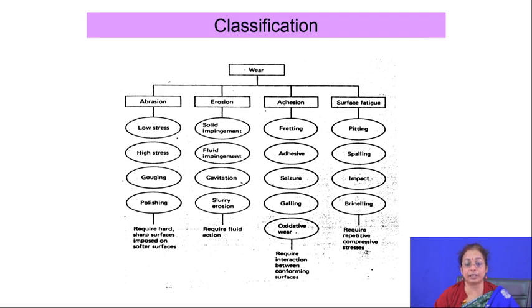If you say that the wear resistance of a material is quite good or quite bad, you cannot define the wear property by a single value as in the case of tensile strength or yield strength. It is very much a relative property. It depends on the environment, the applied load, and the sliding velocity. So many factors come into picture, and finally it also depends on the material-to-material combination you are using. Wear modes, in summary, can be divided into 4 different categories.